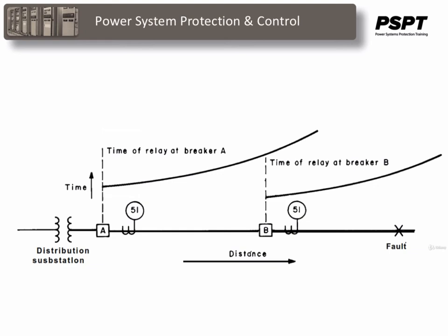Something else that relay designing has to take into consideration on such simple feeder setups is that after such a feeder has been out of service for a long period of time, especially in the winter when things are cold, and the off period of all intermittent loads is a long time, such as furnaces, refrigerators, pumps, water heaters, etc. Then when the breaker is closed to re-energize that line, these feeder loads are all calling for energy all at once, and the normal diversity that the feeder would experience as things come and go in proportional times isn't experienced.